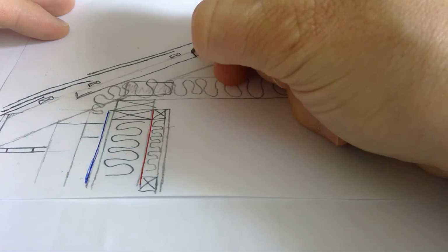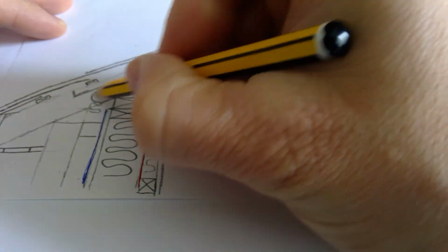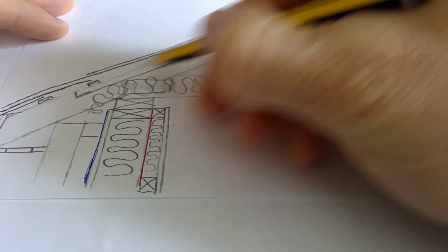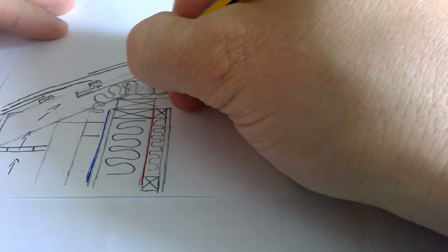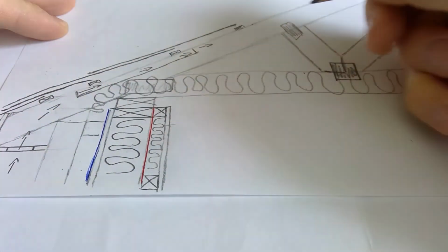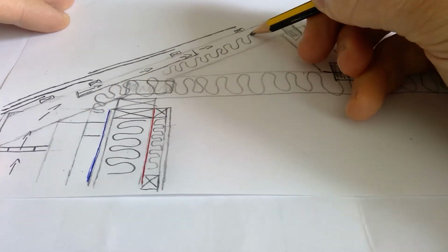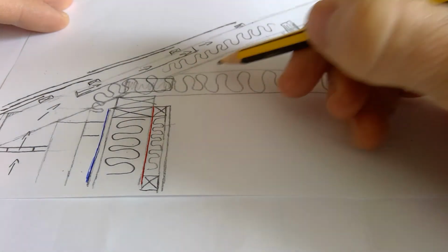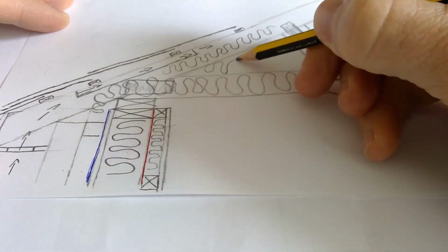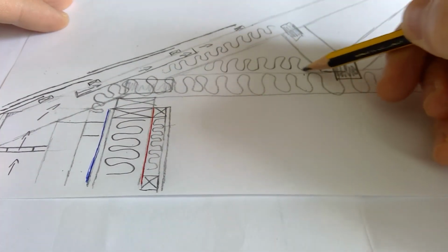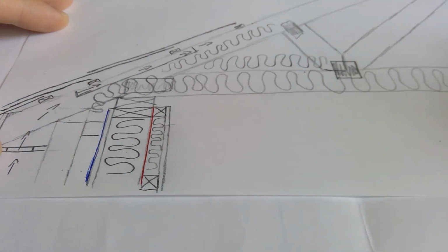Again, where does it go exactly? Make sure that it's before this insulation and after it, so it can carry air over that insulation. Usually 600 or 700mm long for an eaves ventilator. It shows so clearly the path of air, so a couple of arrows if you want to show that. If you want, it doesn't ask specifically, but sometimes insulation goes up along here. You can add that, or sometimes there could be a second layer of insulation on top of that. You can add that if you like. It doesn't ask specifically for it, but you can add that in if you like.